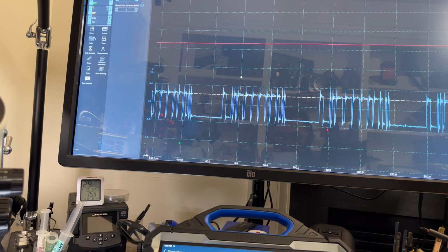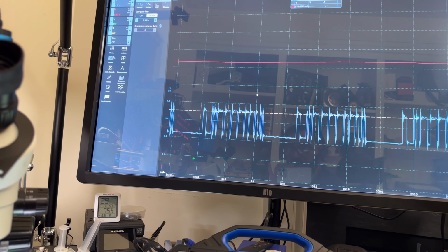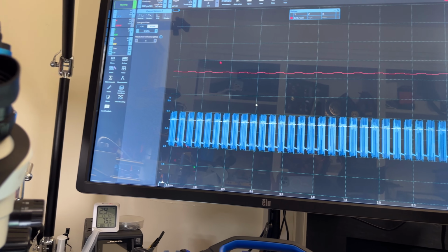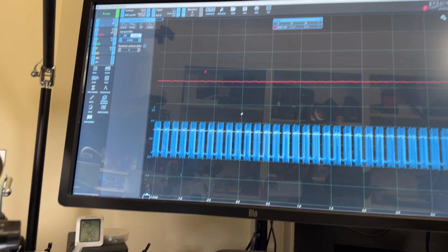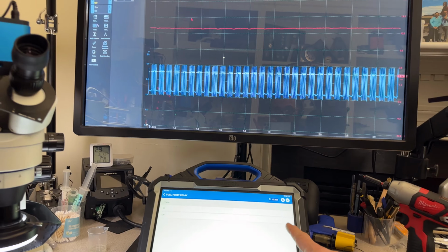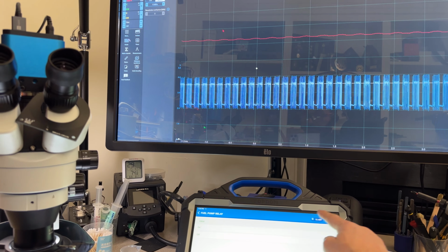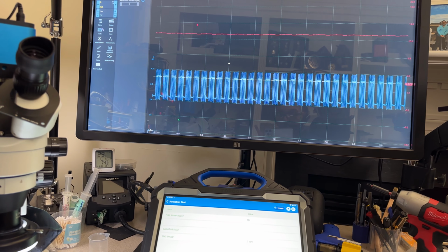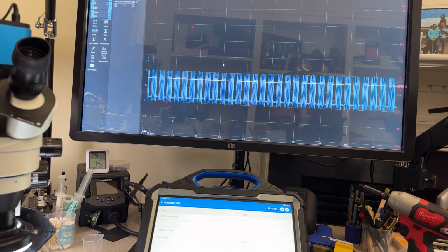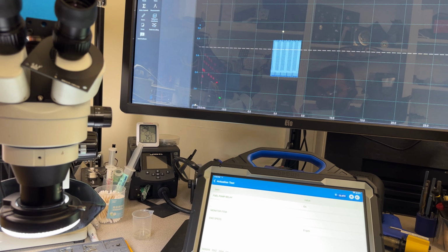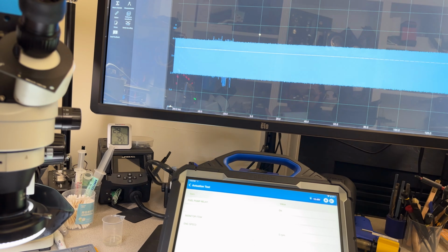All right, so I'm going to do the activation. I'm going to change the time base because this is too fast for seeing that on the screen. All right, yes, you guys are seeing that. Probably a little bit like maybe right there. My hand doesn't reach. All right, so we're going to execute the test, and we can see the activation. Still 500 microseconds is too much because it's just a relay. So let me stop it.